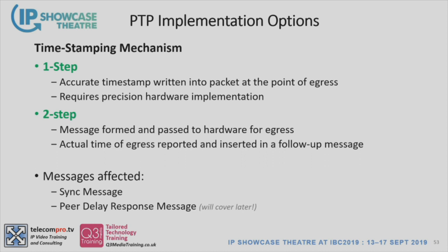It takes time to work through a system to get out onto the wire, and that introduces inaccuracy in that time. So what some systems do is redesign it at the hardware layer so that they can insert that timestamp very accurately at the point that it leaves the device, and that's called the one-step mechanism, because it's able to do that.